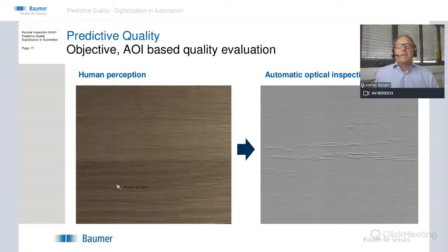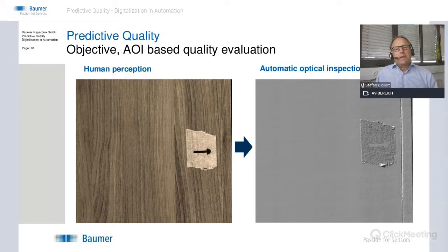Of course, here we have a foil wrapping, seen by our automatic optical inspection, AOI. As you can see, you have here these wrapped foils, and of course that leads to a reject. Maybe you have to go back into your process and change it to avoid that. Coming back to what we see here, an open edge, or no, that is an open foil. Also this is from the quality handbook of our customer. It's too much, so that also leads to a reject. Because here you see more or less the same colors, it's really hard to decide immediately product by product.